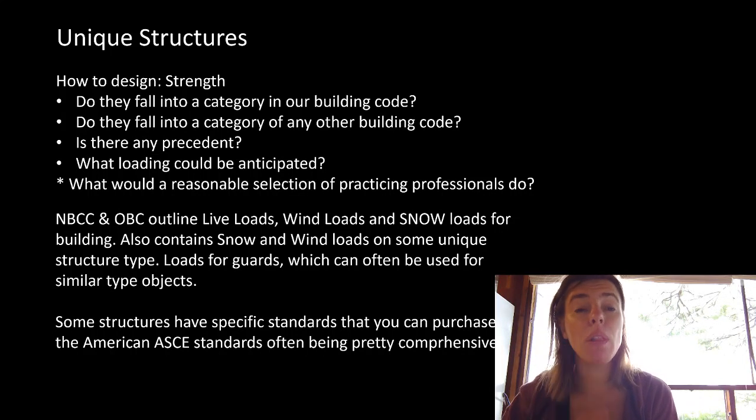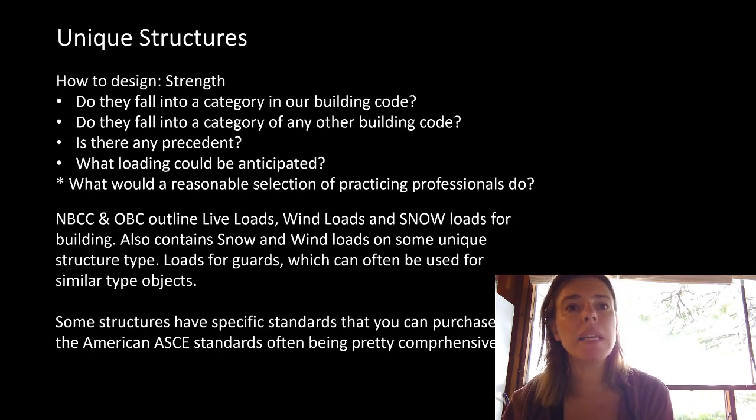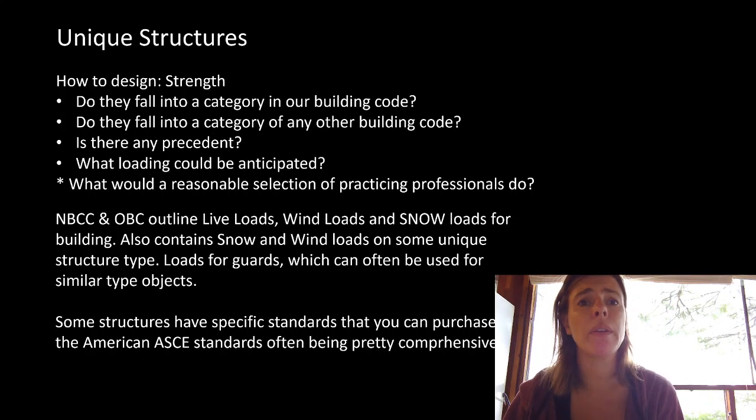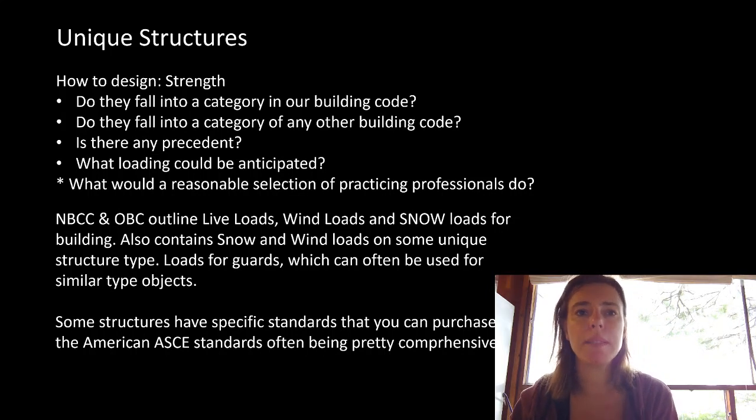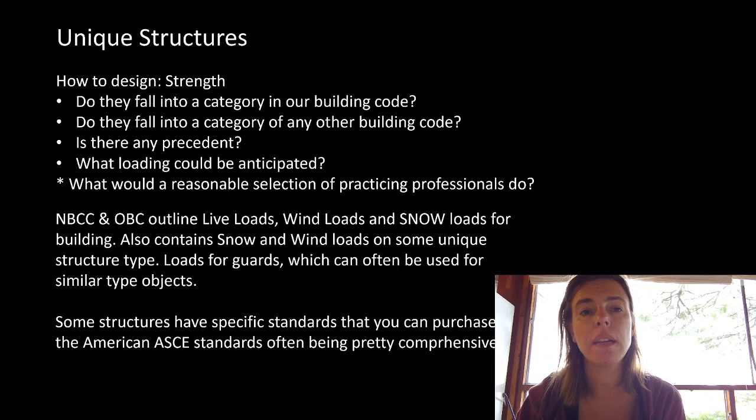I've often colloquially or jokingly referred to that load as the one drunk guy factor or one drunk girl factor. Basically, you get people running around and they decide to climb a thing that they would reasonably not do on a normal day. Inevitably, they will try to decide to climb something if they can. And so we design it for a person getting into this structure and hanging off of it.